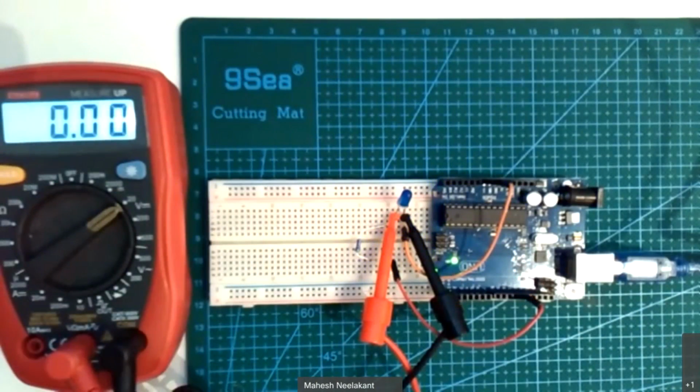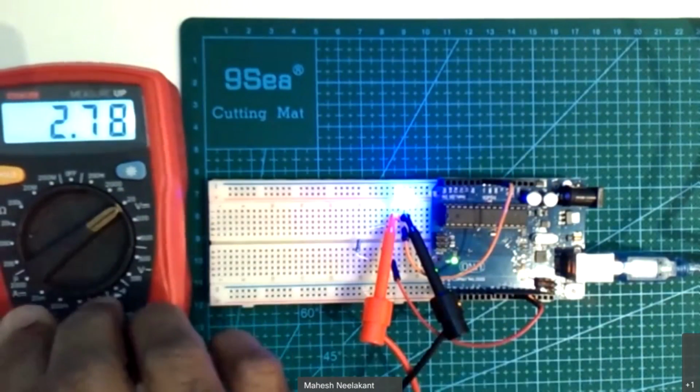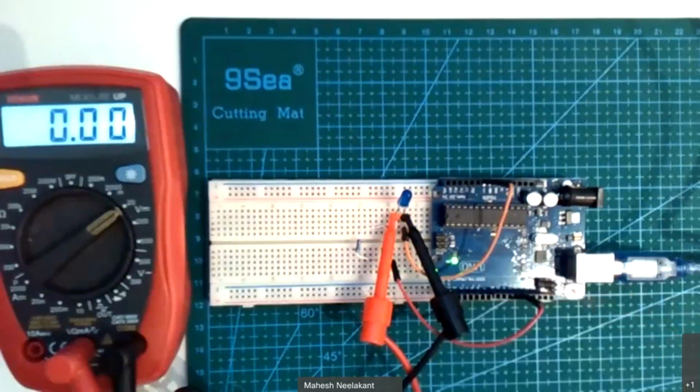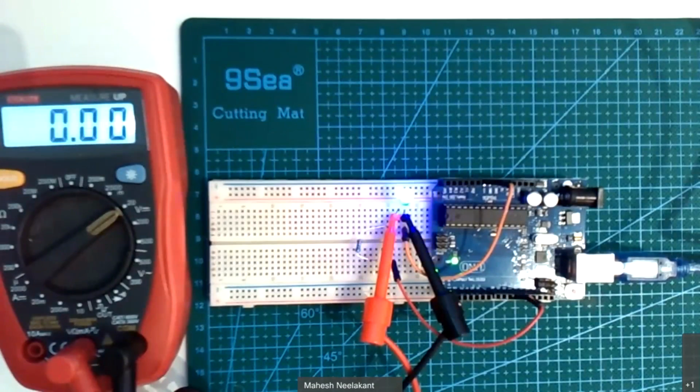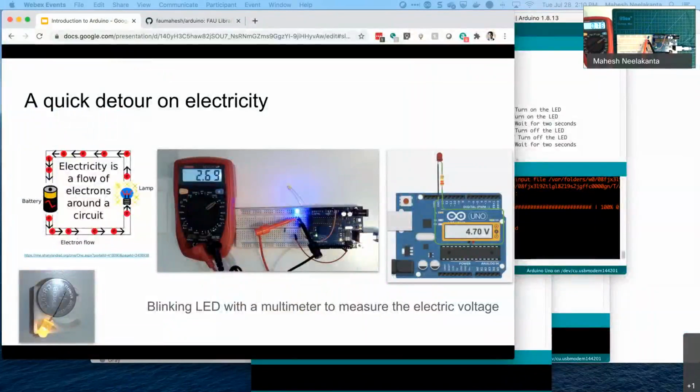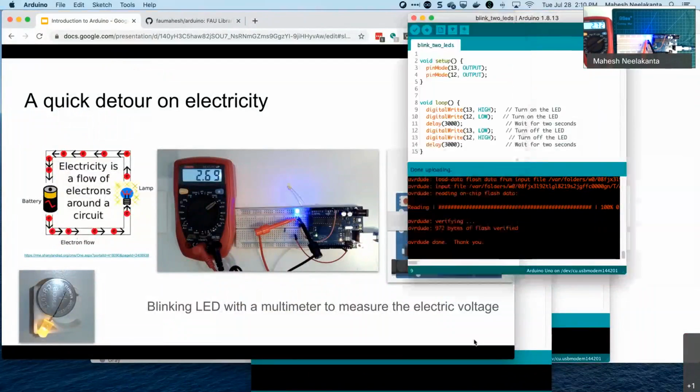So what do you see over here? And I can start this device. Actually, it's already running. The Arduino that we built that blinked an LED. Let me share my screen again. It is basically this code right here. It sets up 2 pins and then turns a pin on or off depending on what we do. High means turn it on, low means turn it off. I've simplified that circuit. I've removed one of the LEDs just for the sake of explaining what's going on. It's the same circuit that we saw before, except I've put what's called a multimeter that's measuring the voltage. It's connected on the negative side and the positive side.